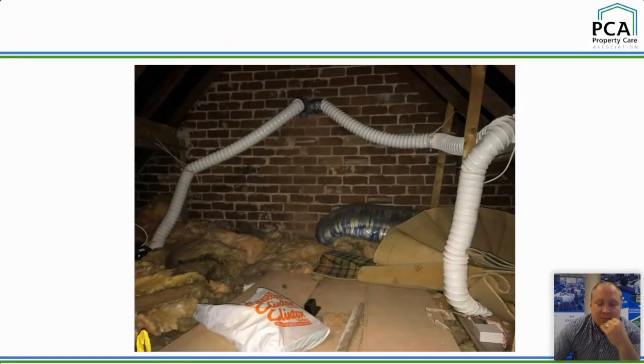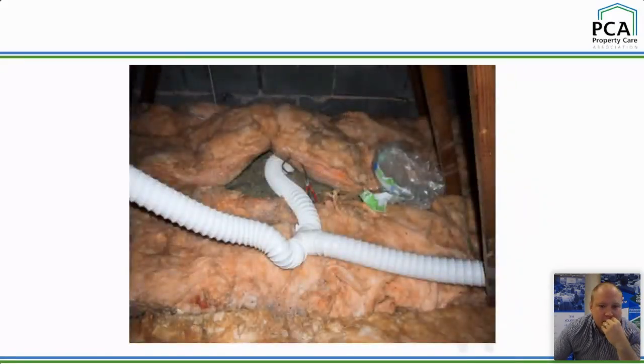Again, a similar thing, well beyond the 1.5 meters. You've got the carpet on the ducting as well, and those vertical traps. The other thing to point out is you've got uninsulated ducting going through a cold void. So you've got warm moisture going up that ducting into that cold void, which is going to cause condensation. And chances are, particularly with these huge vertical drops, you're just going to have condensation running back out your fan. I know there are numbers of videos online where you've got condensation running through extractor fans, water running back out. So another thing to look at.